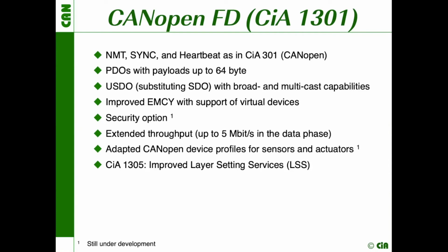The advantage is not only that the Universal SDO now has larger payloads, there is also another very important part of why USDO is better than SDO. With SDO, we always had, in a predefined connection set, only a setup of an SDO connection between one manager and multiple clients.